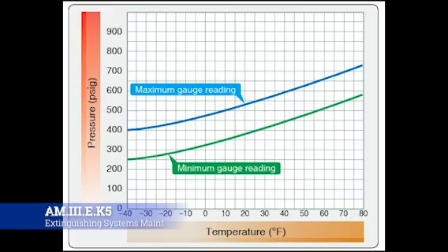Now, sometimes you may have to do a little interpolation depending on the type of aircraft, or if it's reading low but you're in some kind of bizarre scenario where you've flown up into the Arctic or whatever, and all the fire bottles are low. It doesn't mean that they're bad. It just means that the temperature has dropped, and if you're going to go right back into a warmer climate, the temperature will come back up, the pressure will come back up. Same thing if you're in Riyadh, Saudi Arabia, the pressure could be super high because of the temperature being super high. So there's this band that you'll want to make sure that bottle stays in.